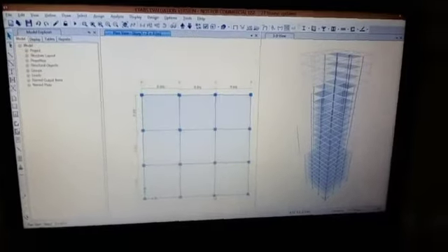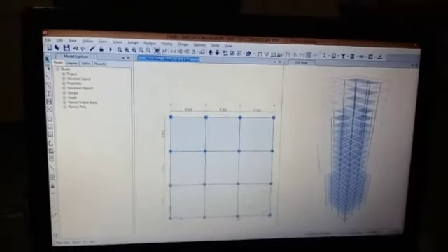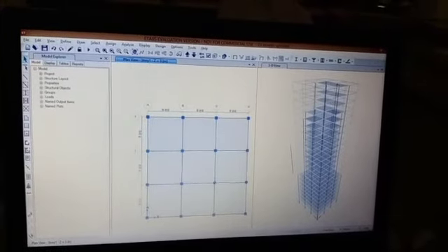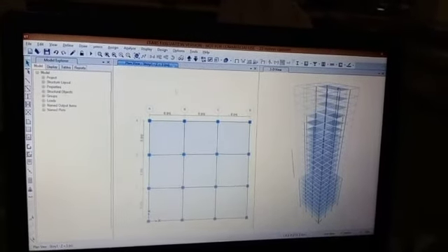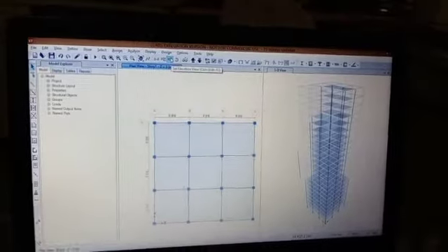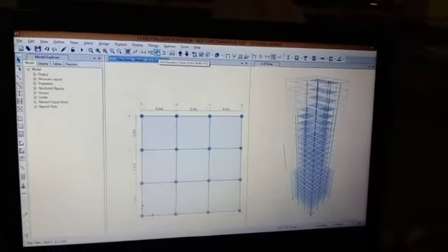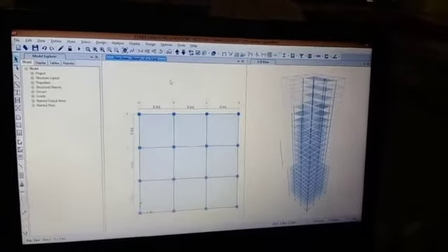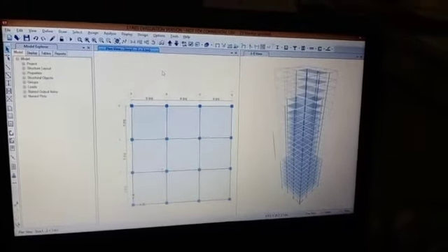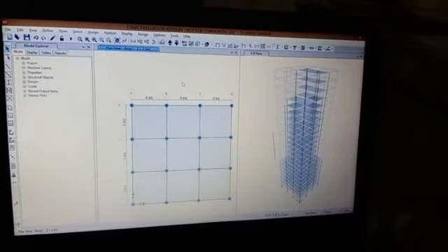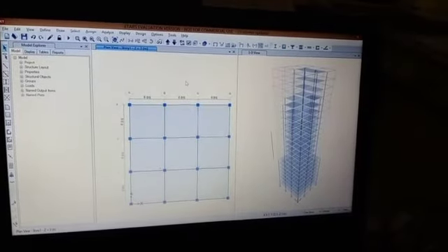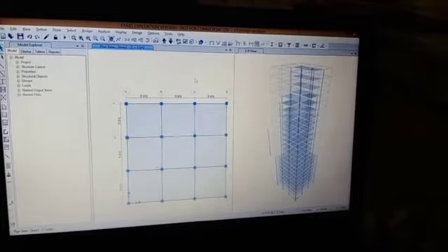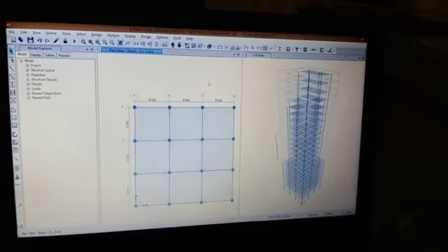Now after defining the wind loads, we have to apply it to the varying sections of the claddings and all the different stories of the building, and this you can do by choosing the elevation option, and then a pop-up is shown which shows the elevation, and then select all stories and select all the 23 stories and apply the cladding load as per the IS code 875 1987.